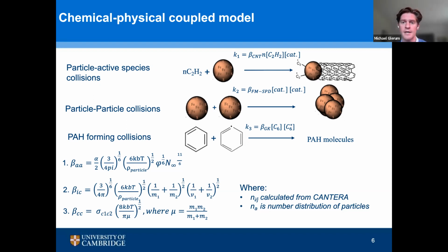To calculate the concentration of our species as a function of reactor axis, we used methane pyrolysis and methane oxidative literature that has been studied before for soot formation. So the chemistry for the C1 to C4 carbon molecules within your reactor is really what we're using for these chemical formation mechanisms.